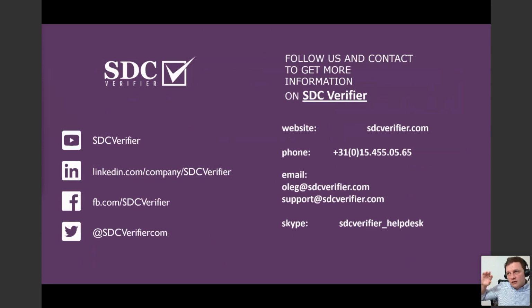And a bit of a secret here: they are all referring in one way or another to the basic code. There is the Palmgren-Miner rule and the S-N curve method for fatigue. What is different between different fatigue standards is just the material properties, S-N curves, and factors and characteristics. So the logic is already there, and we are happy to add that for you if required.